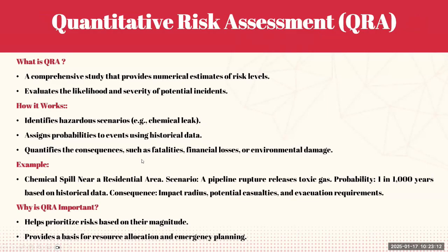Lastly, we have the QRA, which is a quantitative risk assessment. It's a comprehensive study that provides numerical estimates of the risk levels. It evaluates the likelihood and severity of potential incidents. How it works is that it identifies hazardous scenarios, let's say a chemical leak, for example. Then it assigns a probability to events using historical data. So this is more quantitative, hence the QRA name.